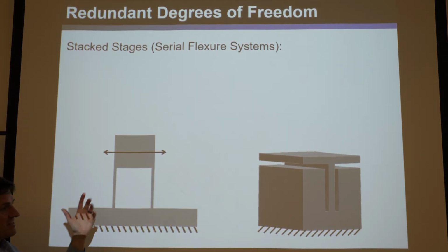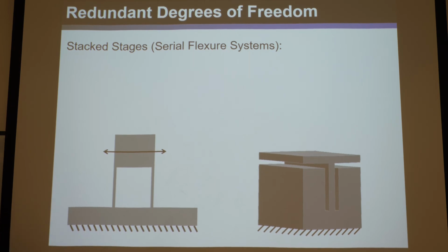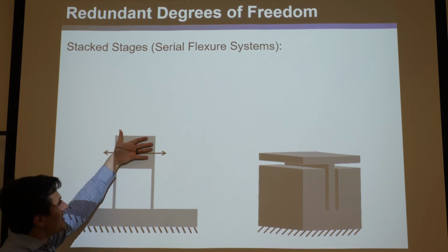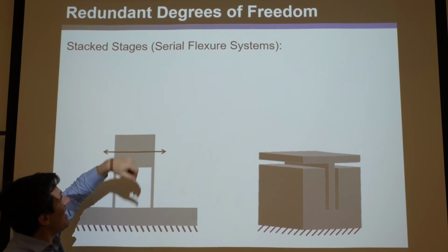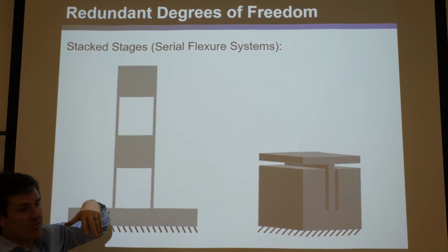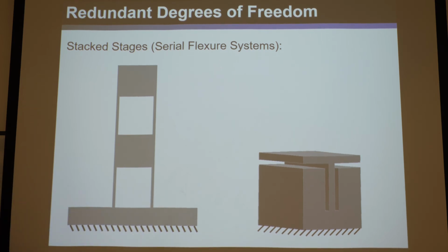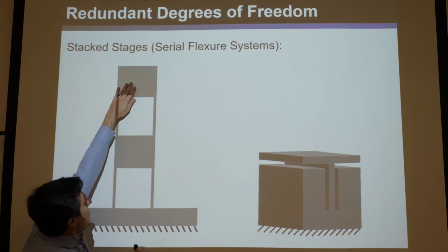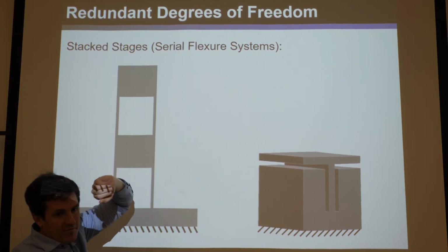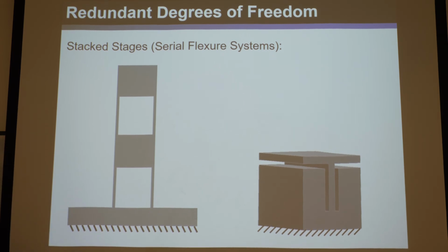Okay, so parallel systems don't even have an intermediate stage to be under-constrained, and they only have one stage to have degrees of freedom. You need at least two stages, two bodies, this one and this one, to have degrees of freedom to even be redundant. Okay, so only serial and hybrid systems can be under-constrained. And they're not always under-constrained. Sometimes they're not, but the way you can tell a serial or hybrid system is under-constrained is there's two conditions. If they have redundant or the same degree of freedom, and if you can hold this fixed with respect to that, and this guy can still move. And they're both the same condition, but it's two different ways to think about checking it.